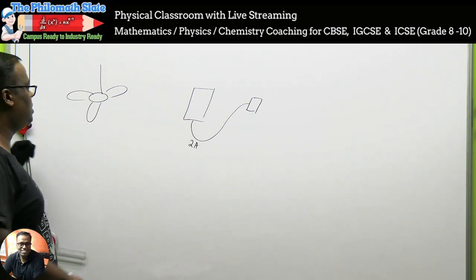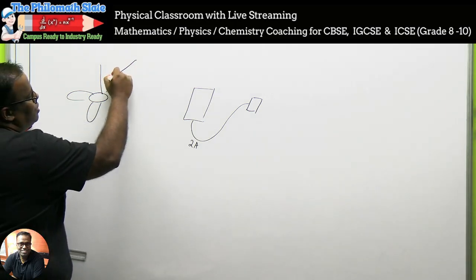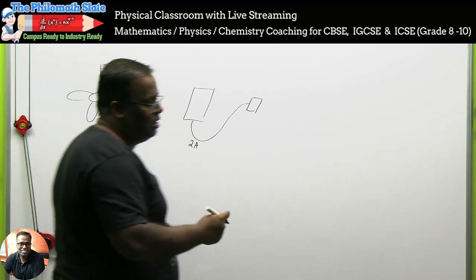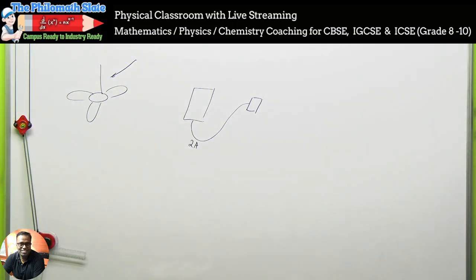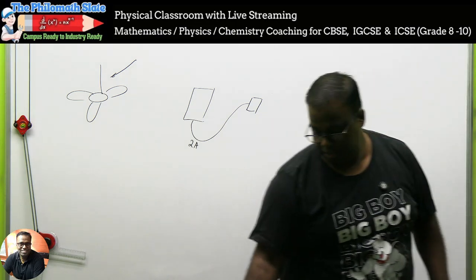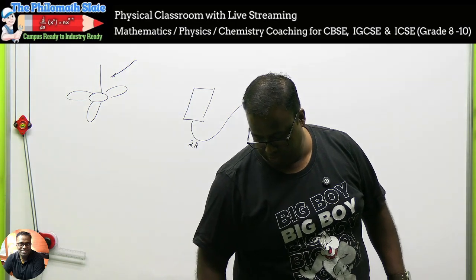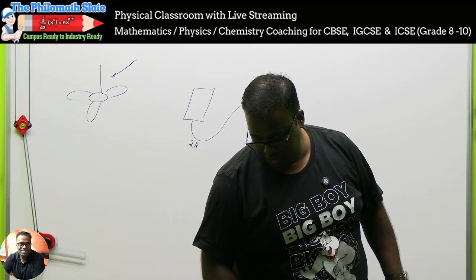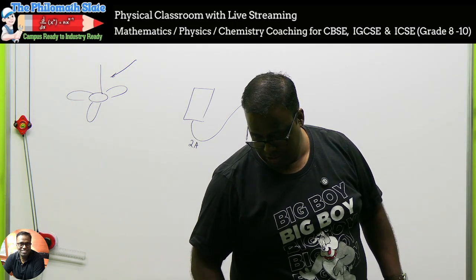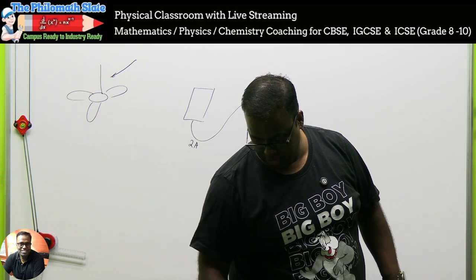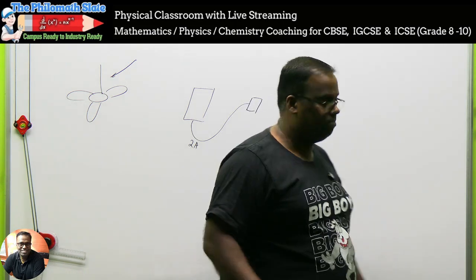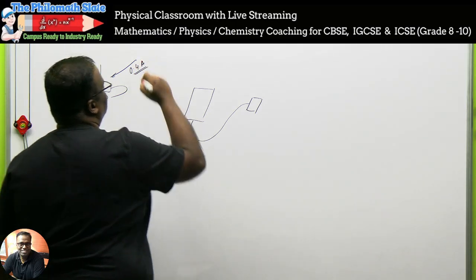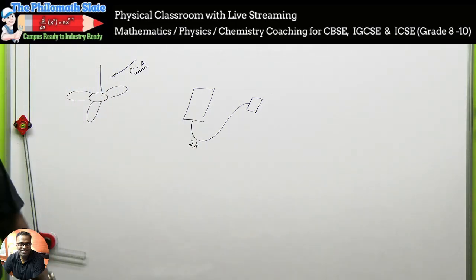If you do the calculation, a ceiling fan draws current when it is fully running. If you exactly want to do the calculation, how much current does a ceiling fan take? So 65 watts divided by 230. So it's this much, 0.2, and divided by 0.8, 0.4. Some 0.4 ampere current it is pulling. 0.3, less than this.